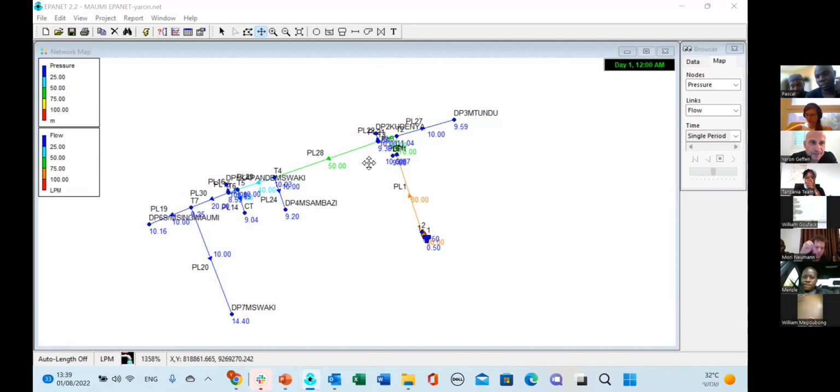You want to take the borehole yield, let's say it's 1 liter per second, times 60 seconds, so it will be 60 liters per minute. You take those 60 liters per minute and divide it by the number of taps. Let's say there are 10 taps, so you have 6 liters per minute in each of the 10 taps, and that's it. We want to use a simplified approach that will have the same demand at each tap. It will make your life easier, it will make the contractor's life easier, and it will make our life easier when checking it. We don't want to overcomplicate things, so I think we'll stick to that for now.